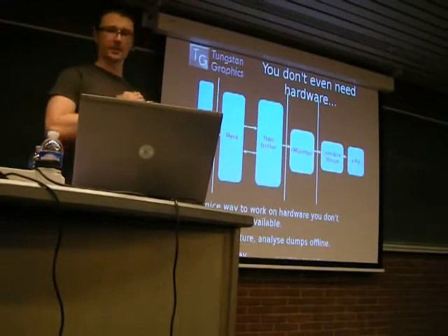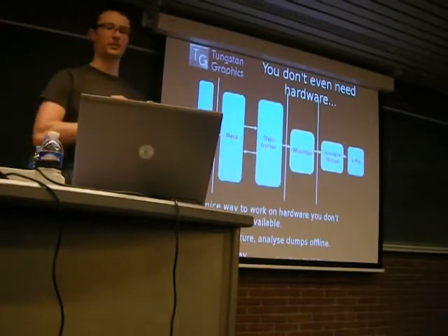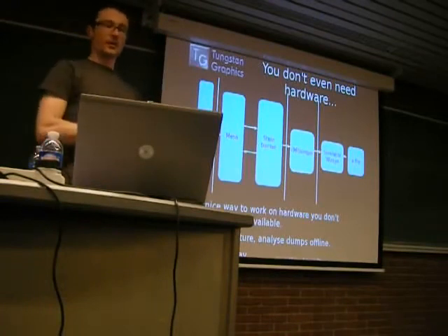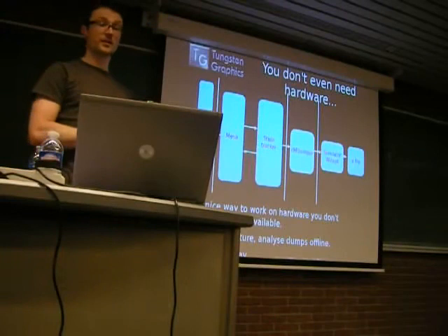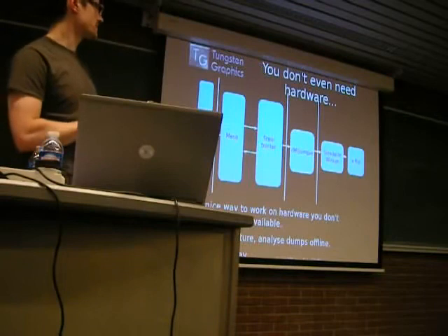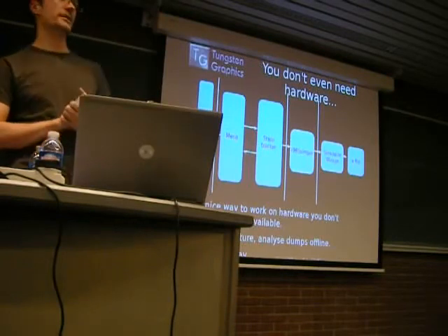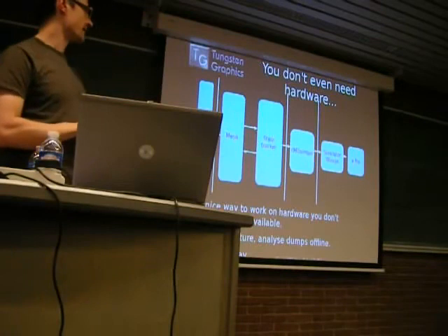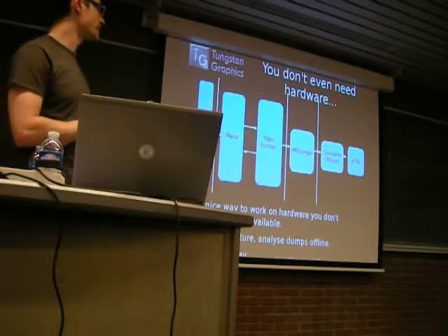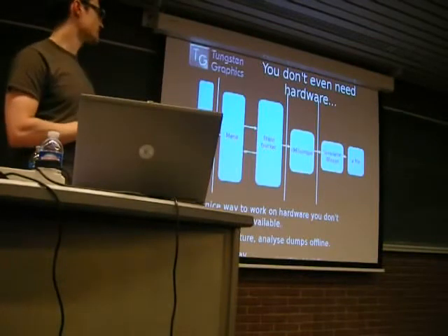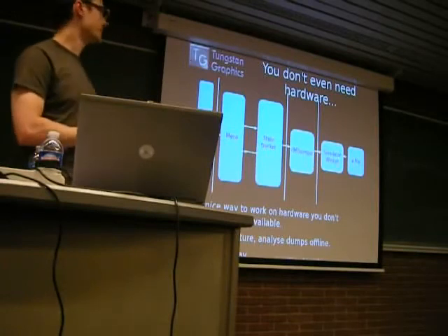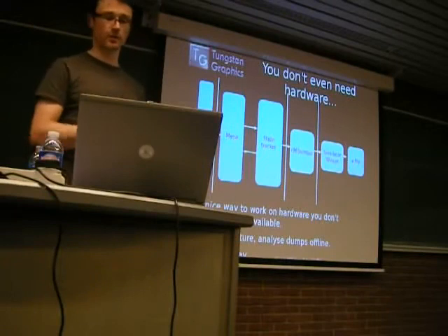And you don't even need hardware. This is probably not that applicable to everybody here, but if you're trying to run a driver, the driver now no longer actually talks to hardware. It talks through a very stereotyped interface that you can put whatever you like behind. So if you want to analyze the hardware interactions by dumping files, if you've got a simulator that runs in a batch sort of way, or if you just don't have the hardware but want to test the driver for some change, that's possible, and this works as well.